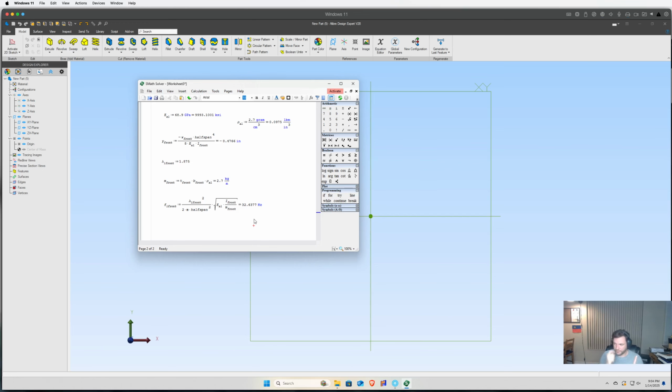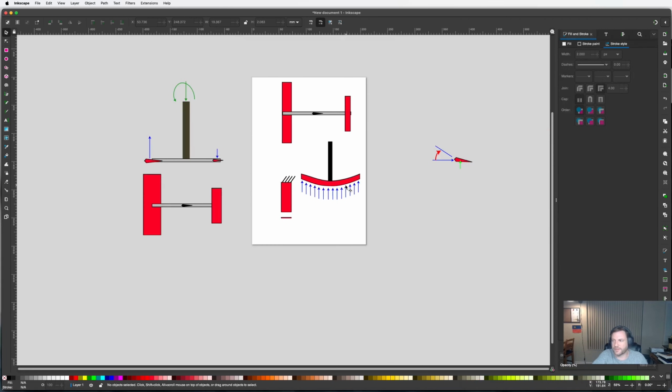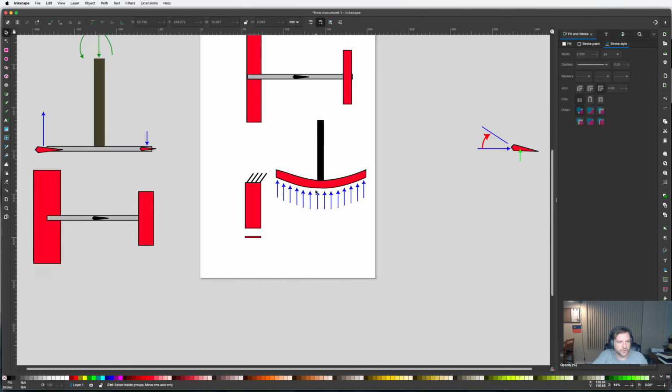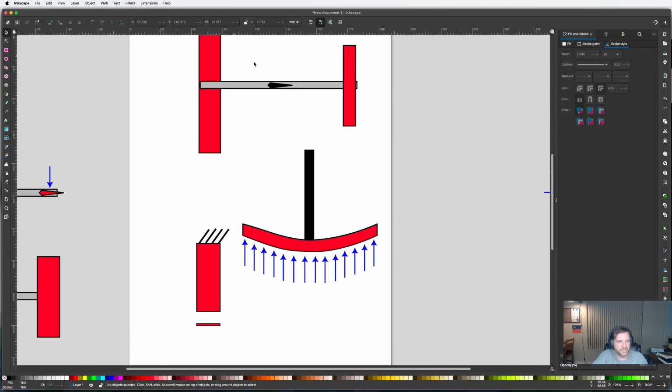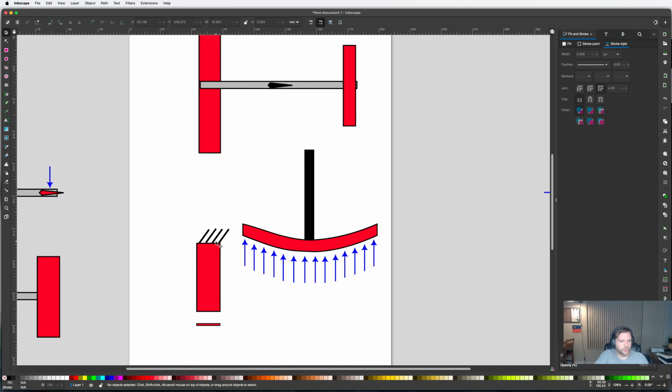Now that's just a bending mode, and that is a really simple approximation here. This is just this flapping mode of this structure. What that ignores is anything else going on. And I'm only looking at the front wing. This whole thing could basically shake around this mast, right? You could also get a torsional mode.